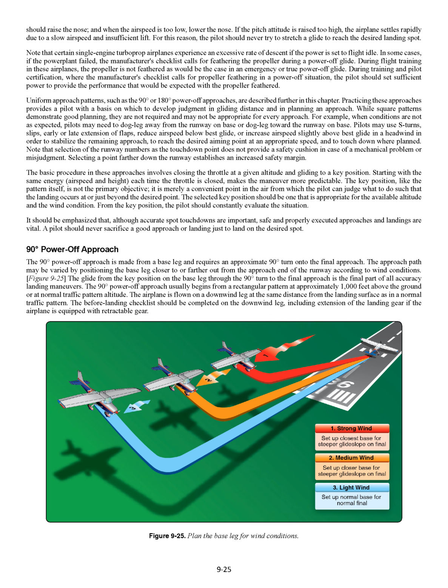From the key position, the pilot should constantly evaluate the situation. It should be emphasized that, although accurate spot touchdowns are important, safe and properly executed approaches and landings are vital. A pilot should never sacrifice a good approach or landing just to land on the desired spot.